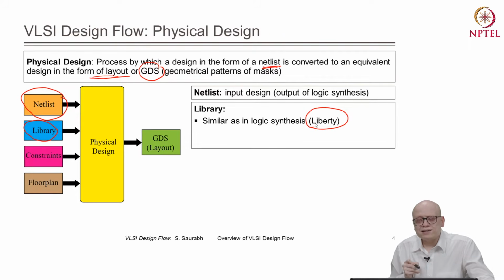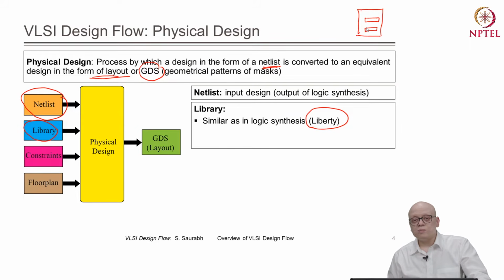And besides the technology library that was used during logic synthesis, during physical design, we also need some information regarding the physical aspect of the standard cells. For example, what is the bounding box for a cell? Where are the pins located for the cells, right? Why we need this information?